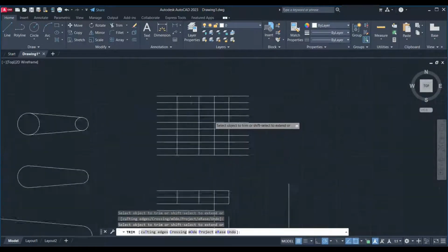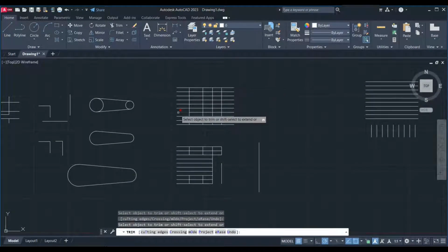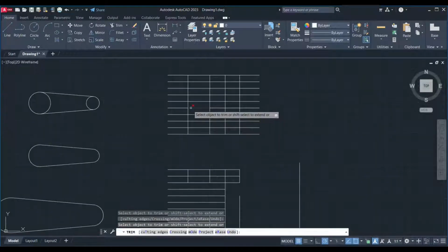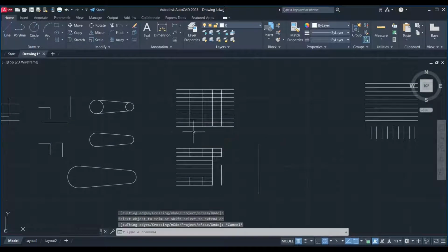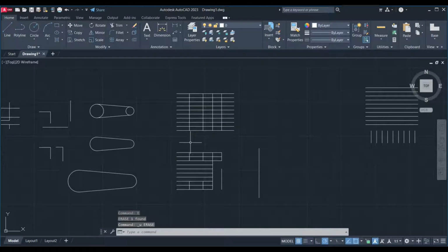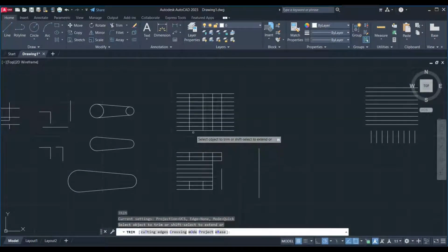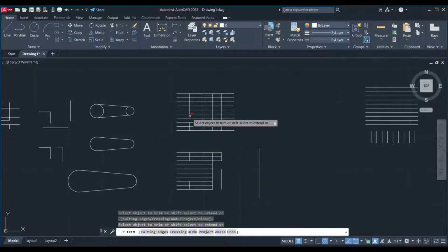Now this one. I wanna change this drawing to this. Guys, here I see that this is a single line. Do you see? So I can't delete part of it. If I use erase command, the line will be deleted. Press Ctrl Z to undo. So I must activate the trim command. Now I have to delete all these parts one by one.